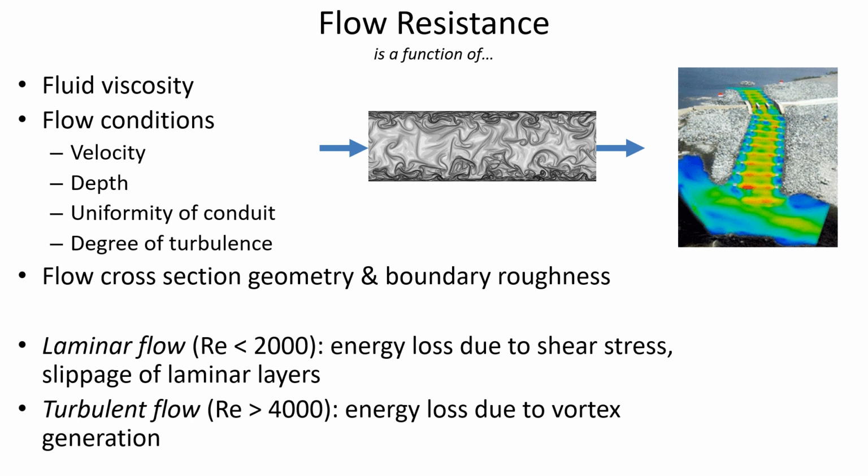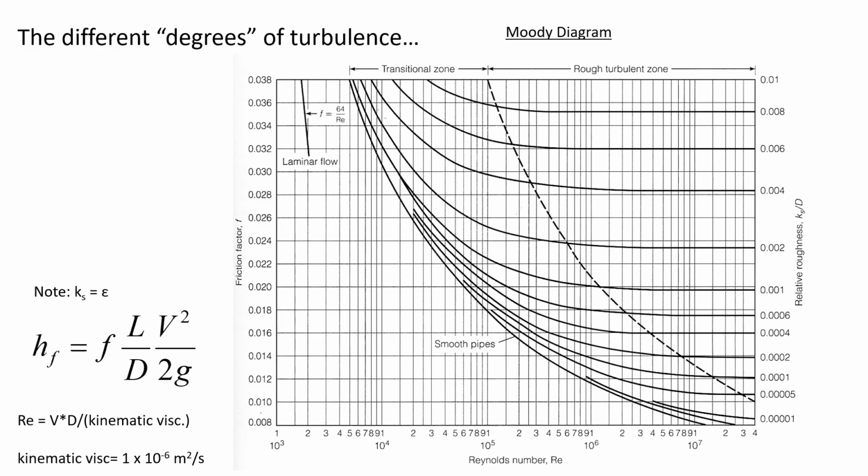You may have laminar flow if you were gradually and calmly increasing the flow velocity after having been in the laminar range. Or in this intermediate zone, you may have turbulent conditions if, for example, the water's flowing through a pipe at a Reynolds number of 3,000, but you're banging on the pipe with a hammer, that could be enough to disturb the flow and cause it to become turbulent.